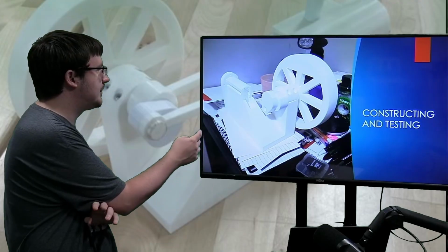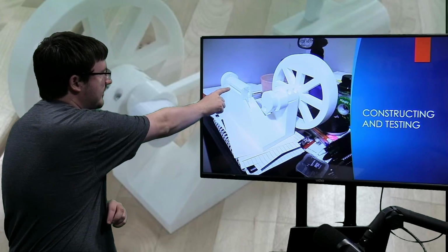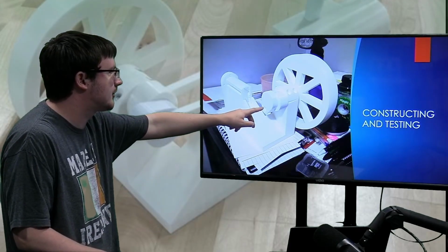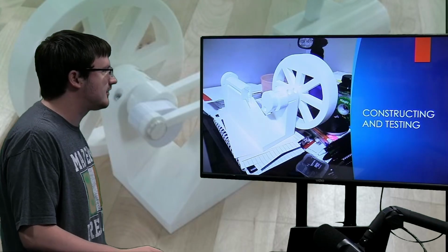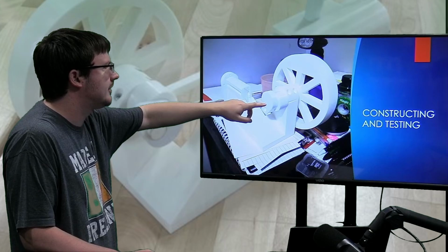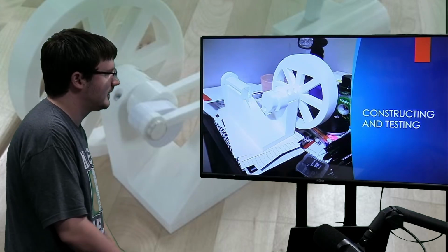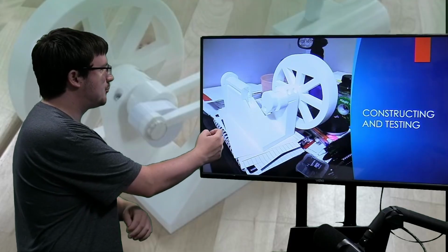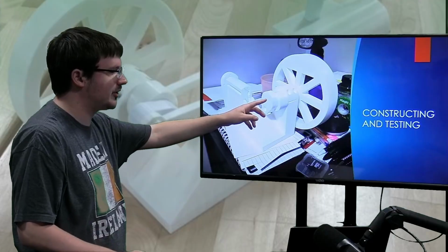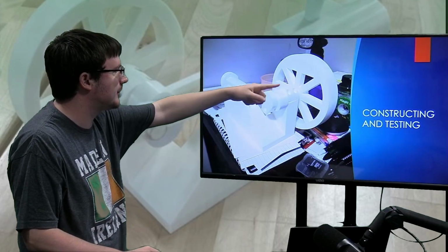The piston then went inside the cylinder through a small hole which you can't quite see there, and attaches to the piston, which connects to the crank here. And on the side of the cylinder is where the valve goes, and the valve connects to its own crank rod, which connects to the crank. And the crank itself is attached in place by the crank cap right there, which is held on by 4 screws, and at the end of the crank is the flywheel.